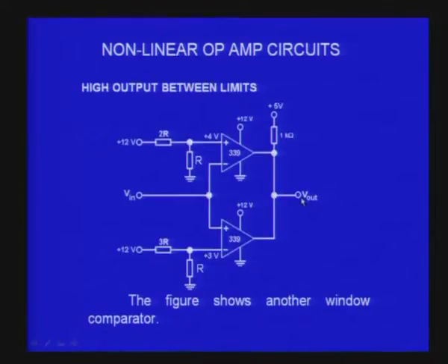So both for the range of voltages less than 3 volts and more than 4 volts, one of the op amps conducts and tries to get plus VCC, and that will make the output transistor to be in saturation, and therefore the output will show almost the Vsat voltage of the transistor, which is about 0.1, and therefore it will be very close to 0.